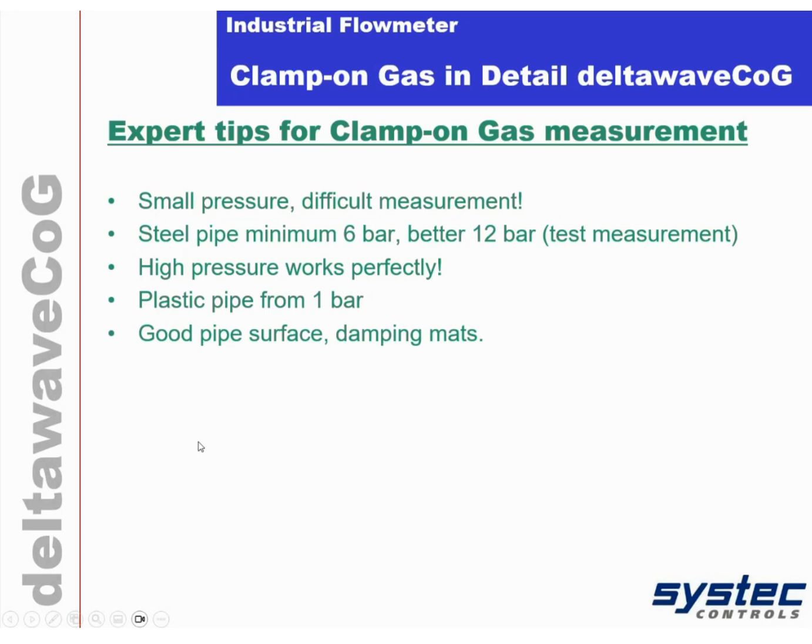Very important for clamp-on gas measurements, prepare the pipe perfectly, make a good surface, make damping mats to make sure that you get the optimum coupling of the ultrasonic signals. For standard mass flow, you need a temperature and pressure measurement.